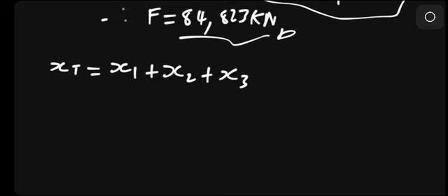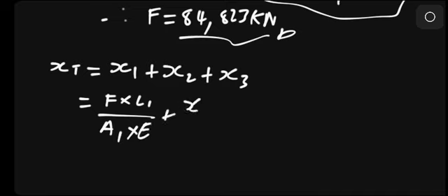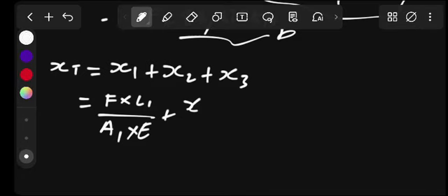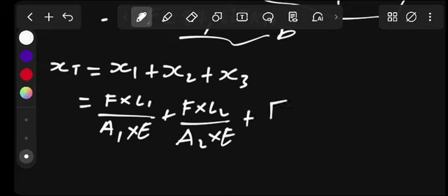The change in length is force multiplied by length L1 over area A1 multiplied by Young's modulus, plus force multiplied by length L2 over area A2 times E, plus force multiplied by L3 over area A3 multiplied by E.